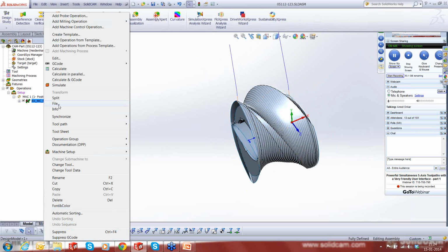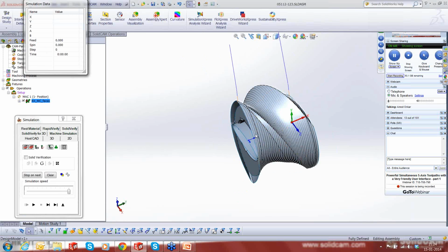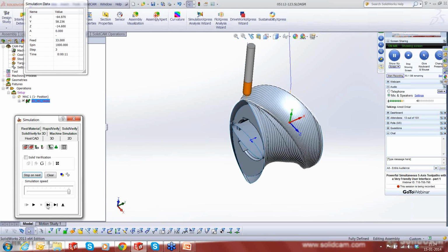And how does this tool move? The tool is going to follow the surface below for motions, but it's actually going to cut the surface above it. So the shape of that surface below will influence the tool movements above it. Using this method, you could have even small bits and surfaces, or the best part is you could have the upper area as an STL geometry, and you could machine that STL geometry in 4-axis without having to create any surface. So this is one of the nice functions inside SolidCAM's 5-axis module.